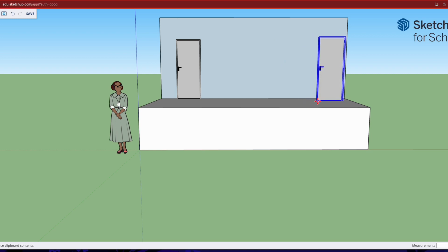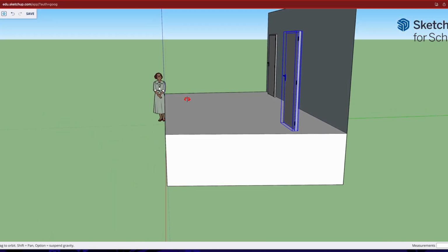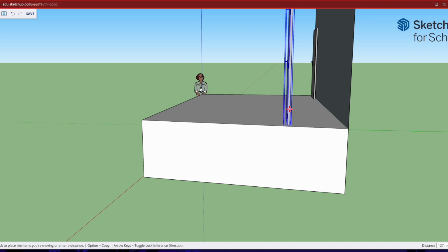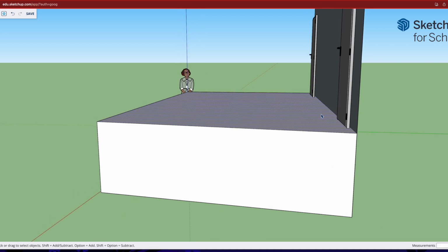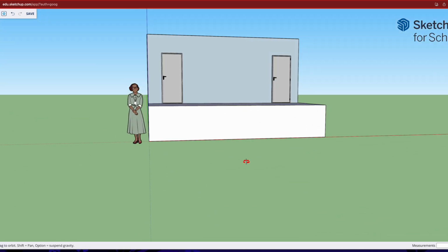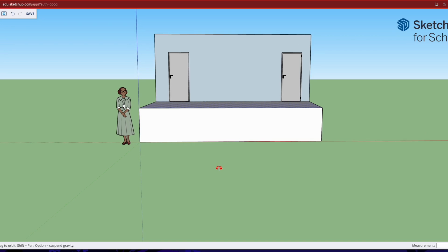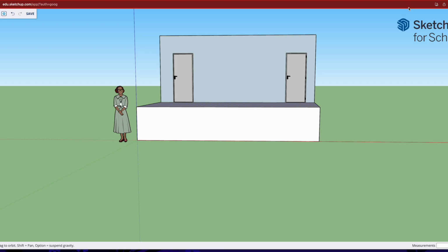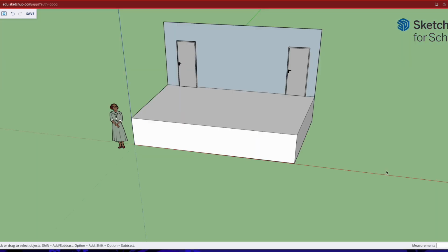So same process around here, and then I select the orbit tool. The shortcut for that, if you want to be a bit quicker, is to press O on your keyboard. Then I come again to the move tool, grab the door with a single click, place it where I want, click on it again, and here we go, I've got my second door in. And then again orbit, change, have a look. I'm happy with where it is right now, and I've got a second door on stage.